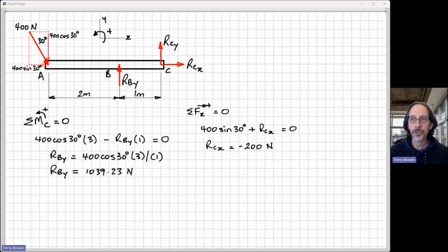Now, what many students attempted to do at this point is to go back and change their free body diagram. Right? You should never do that, because all of this work that you've done here is based on what you originally drew on your free body diagram. So if you change your free body diagram, you've then got to go and change all of these equations, and that's likely to lead to errors. Right? So don't do it.